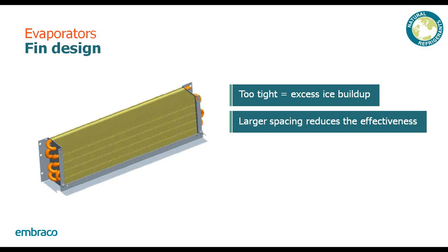There is some free software called EvapCond, which you can download and use to help analyze the design of your evaporator and determine its effectiveness. One thing to consider too is with your evaporator, pay attention to how the fins are designed. If you have cut fins or wavy fins, you get a better heat transfer because you're creating turbulence with the air. The greater the turbulence of the air going through the evaporator, the better heat exchange you will see with the system.